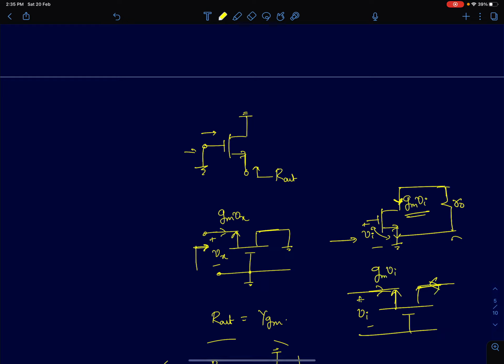So when you apply a positive voltage, your source voltage, the AC voltage is higher than the gate voltage by say Vi volts, then you can picturize in your mind a current flowing from source to drain of value GmVi. Now this does not include the current through R0, it's only the MOS transconductance behavior. So first, let's ignore R0.